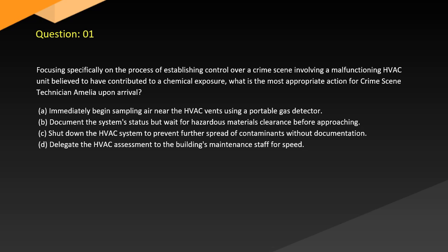A. Immediately begin sampling air near the HVAC vents using a portable gas detector. B. Document the system status but wait for hazardous materials clearance before approaching. C. Shut down the HVAC system to prevent further spread of contaminants without documentation. D. Delegate the HVAC assessment to the building's maintenance staff for speed.